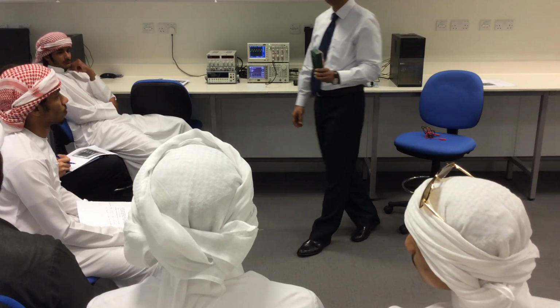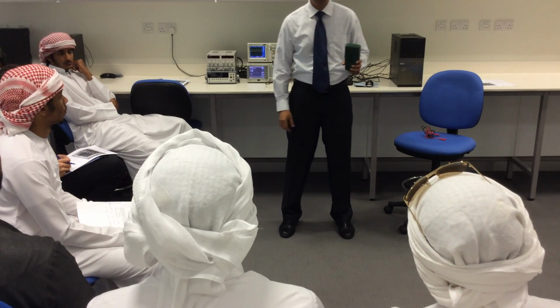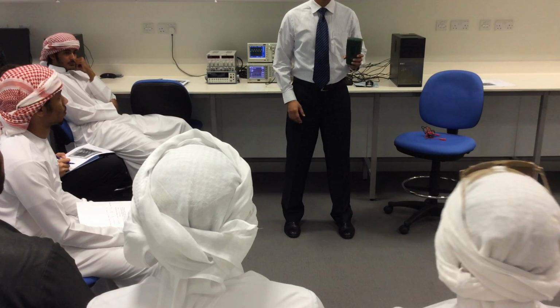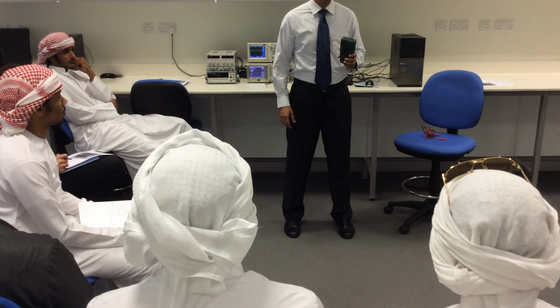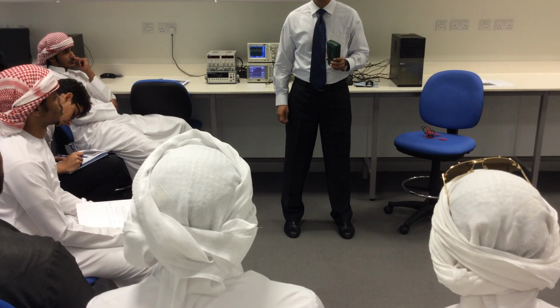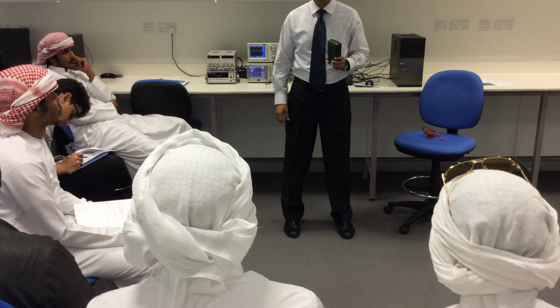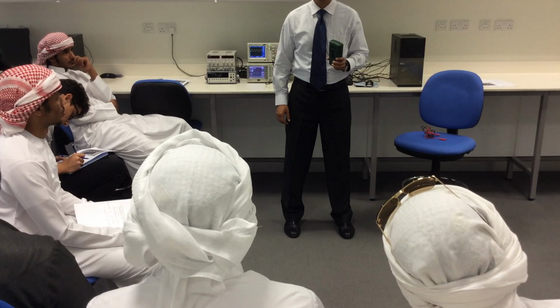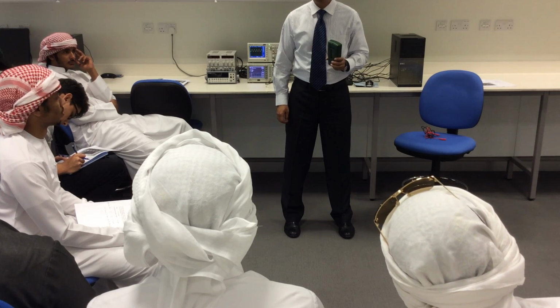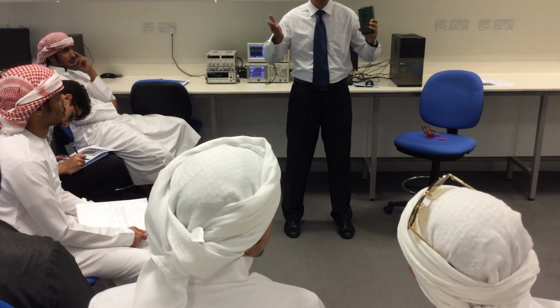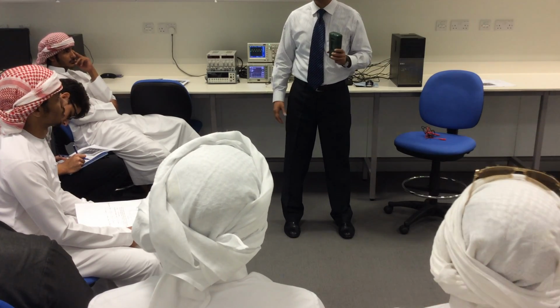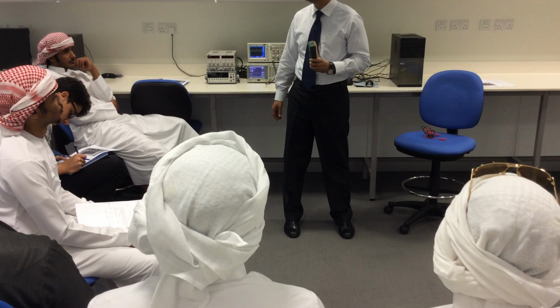Now you have 50 divisions and the full scale is 10. So each division represents how much voltage? 10 divided by 50. You have 10 volts and you want to divide it into 50 divisions. So 10 divided by 50 is 0.2 volts.